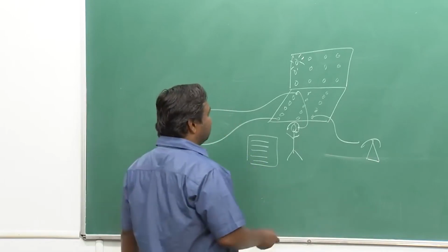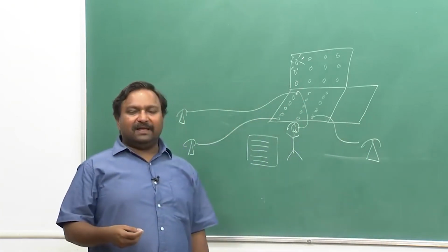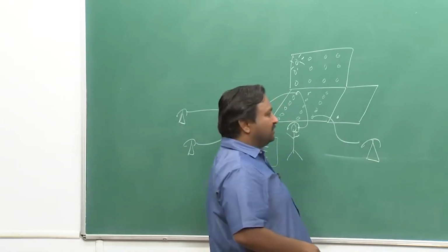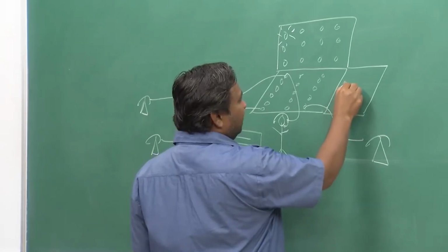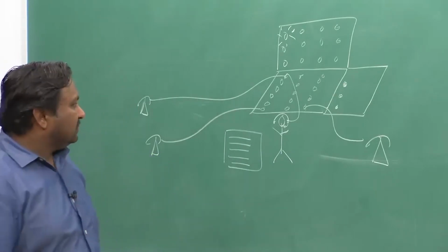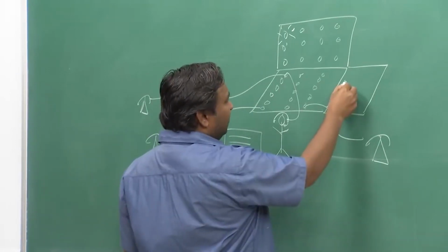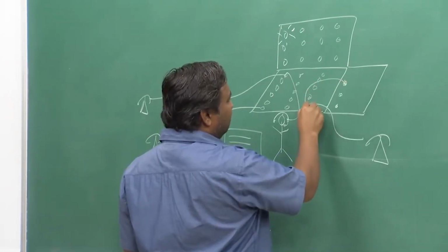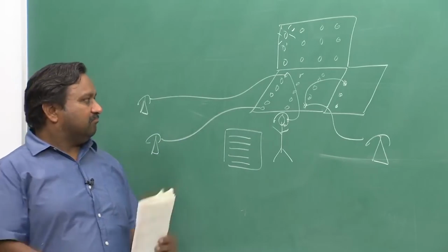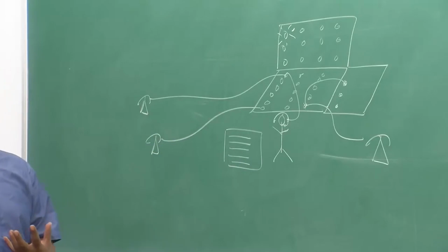So, normally there will be an extension on this board. We will have special generators. So, I can have some kind of music. If the jack is connected to this, you are actually going to listen to the music. There can be radio, there can be an electrical power signal, a ringing current, an oscillating AC. So, she will actually inject this ringing current. She will take a jumper, conduct this ringing current, and then connect to this subscriber. The power signal will go there, which can actually drive an electromagnet, which will cause the ringing to happen.